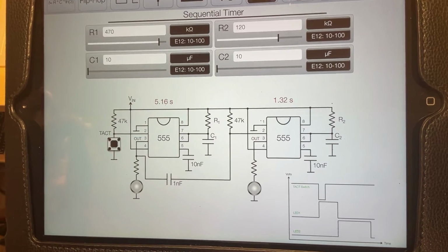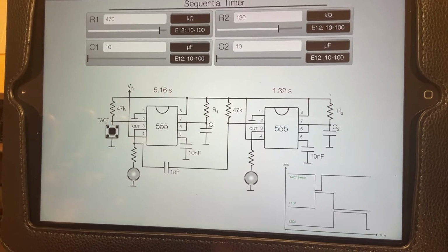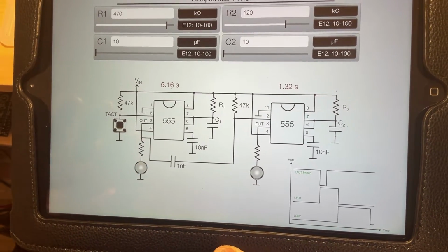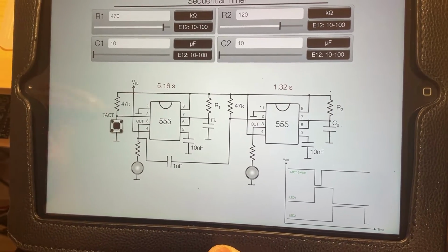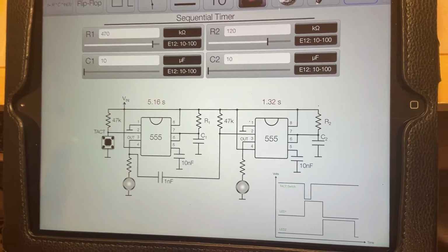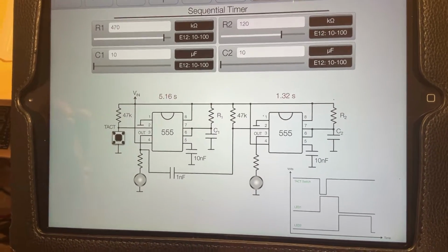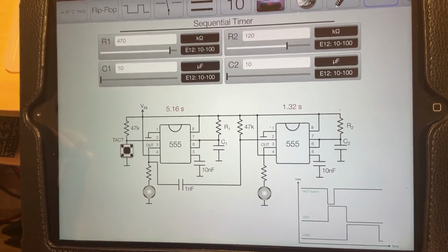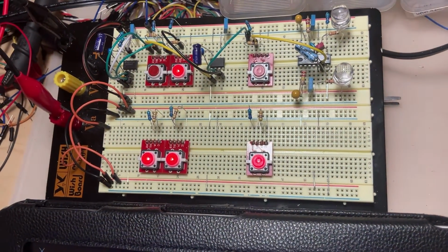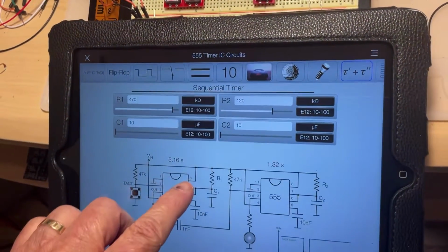I have a special package, the ZSCT1555, which starts at 0.9 volt power supply. This is made for portable stuff using only one AA or AAA battery. This is why the voltage goes so low. But usually there is a standard 555 package like the LM555, which is based on bipolar junction transistors, BJTs, or like the one I chose for my experiments right here, the TLC555, which is the CMOS equivalent, okay?